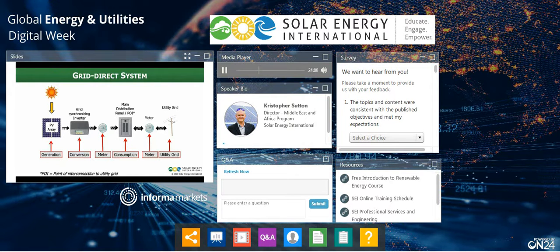We're going to go through the next thing to the right, which is a meter. A lot of utilities want to see a secondary meter. The inverter itself has a meter on board, and so you can get readings off the inverter, of course, of its own production. But often utilities will specify that they want a secondary production-only meter. That meter is measuring the total output of the AC side of the solar electric system.